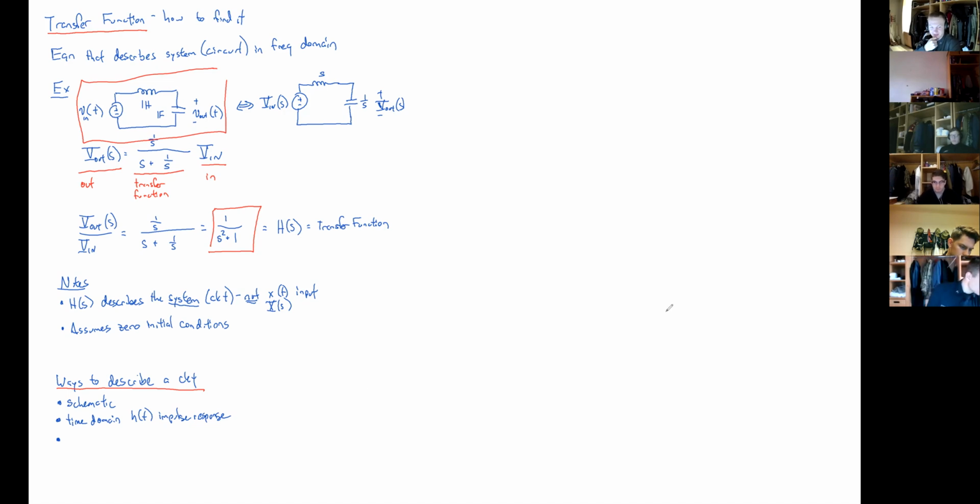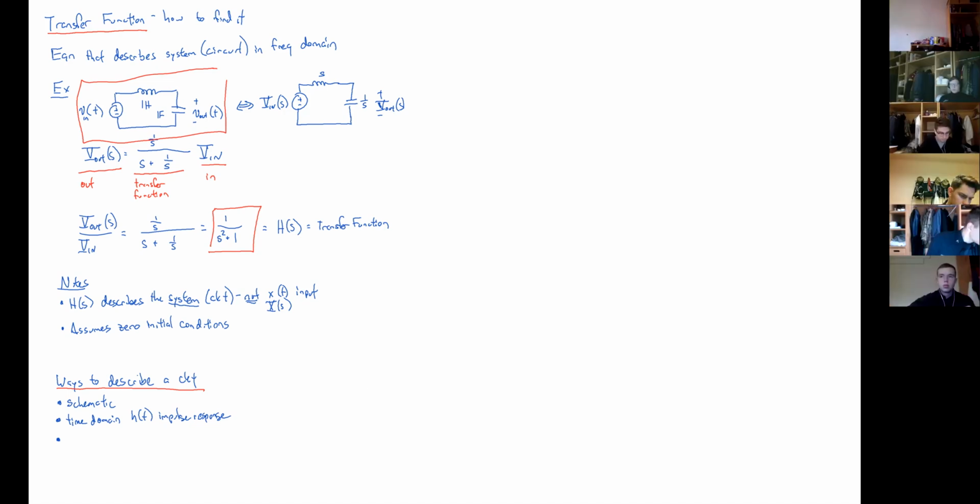But that's okay. I thought what I was trying to say with the t within, for example, if that function is like y, you're going to put the t inside a parenthesis. Well, y of t makes sense. Y of t is the output, but we're not interested in any signals. We're not interested in an input x of t or output y of t. We're interested in only the thing that changes any input to any output. And so that's our impulse response, h of t.